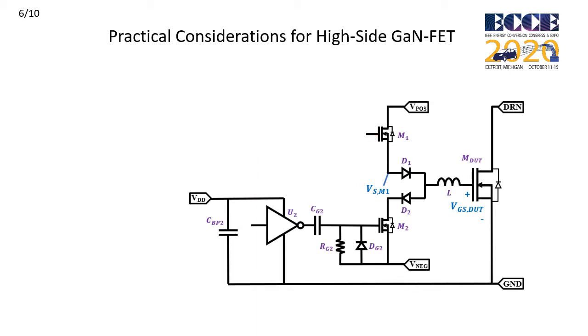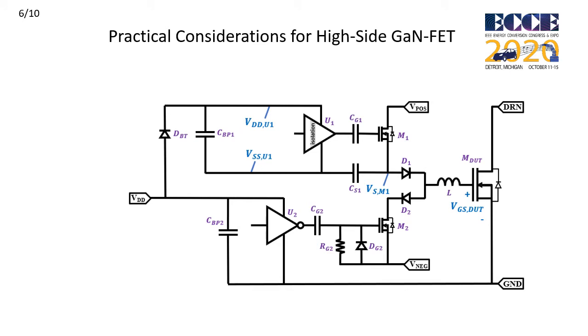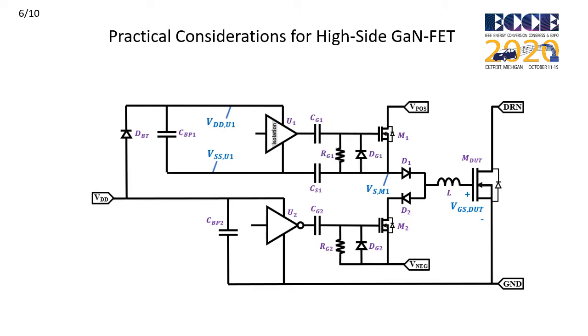So taking inspiration from what we did for the low side switch, we can apply a similar capacitive decoupling technique to the high side switch M1. In this case, we add 2 more decoupling capacitors and some small passives to set an appropriate offset. Unfortunately, a problem still remains.